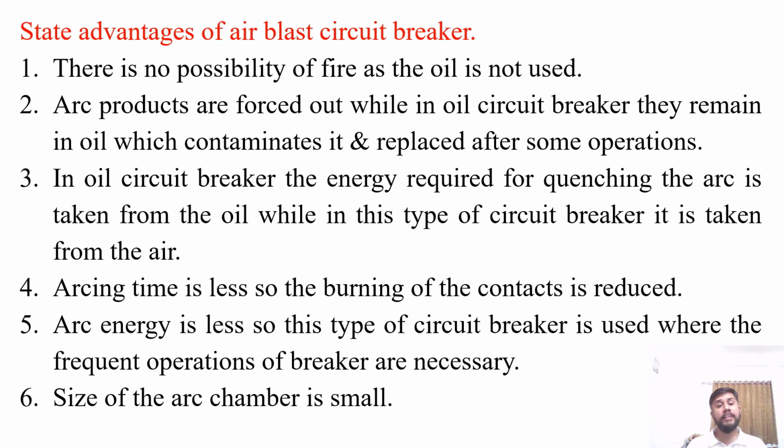So there is no possibility of fire as the oil is not used in case of air blast circuit breaker. Arc products are forced out, while in the oil circuit breaker they remain in oil, which contaminates it and it is replaced after some operations. So the arc products are within the breaker contact and the wear and tear and carbonization forms, due to which the maintenance is very high in case of oil circuit breaker,